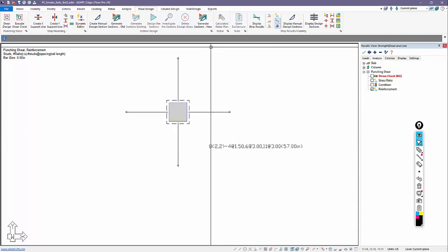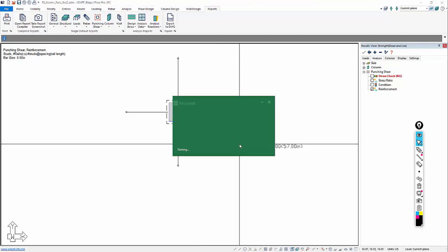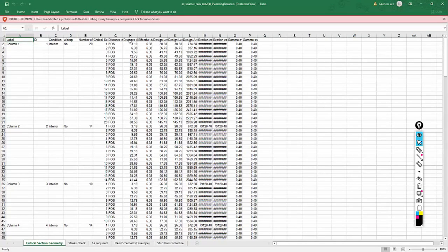And if we go back to the report, we can see that this is again for column 1. We build up the design area up to section 9, and then it drops. So at section 9, this is where the rectilinear section passes the allowable stress. And again, this is the implementation based on codes ACI 318-11 and prior. And then we introduce this octagonally shaped section where we now check the first octagonal section, second, and this actually builds out until we reduce the stress to 2 square root of f'c.